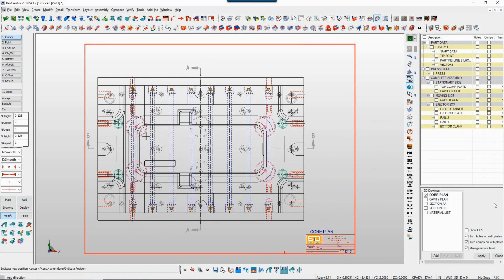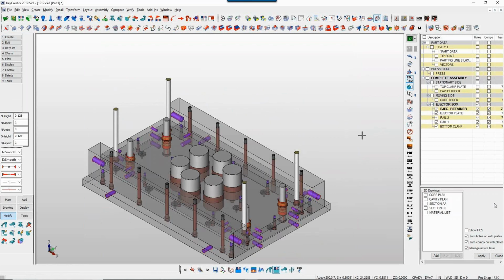So I'm going to say by group, and I'm going to move, as you can see, because I picked by group, it picks 4 pillar supports that are symmetrically opposite about each other. And I'm just going to move them super close together. And just the reason for that is I want to be very drastic so that you can see the difference. So this is done in 2D, but now when I switch over to my 3D, it's updated as well.